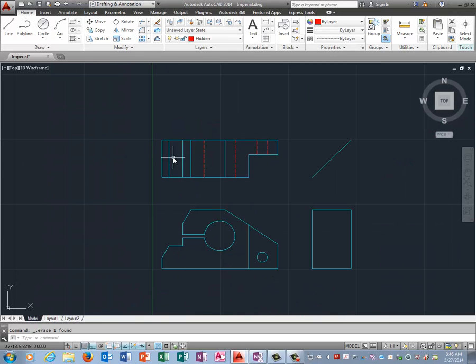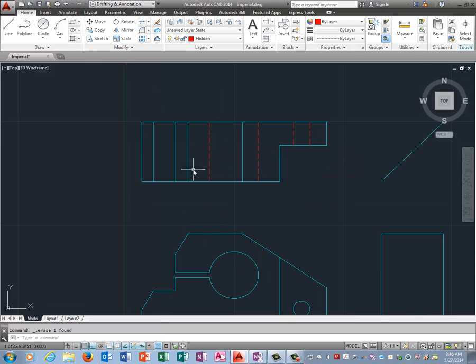Okay. Now we have this circle up in the top view where it says C-bore from bottom. What that is, is a counter bore, but the counter bore is upside down. You guys are used to drawing them where the counter bore sits up top. This time it's at the bottom. So the way we're going to draw this is we're going to figure out first of all where they go. And because everything on this drawing seems to be measured from the center of this circle, yay, we're going to drop a line here.